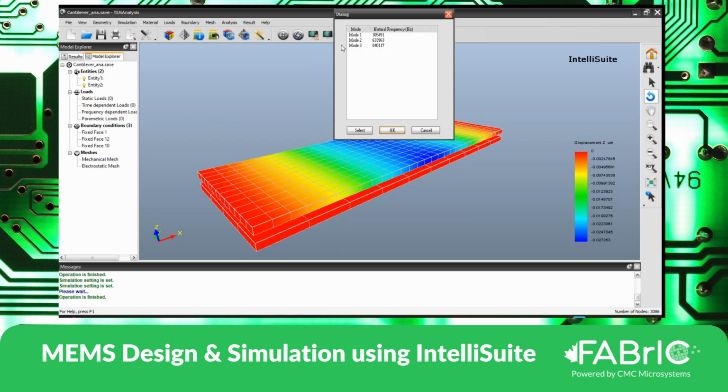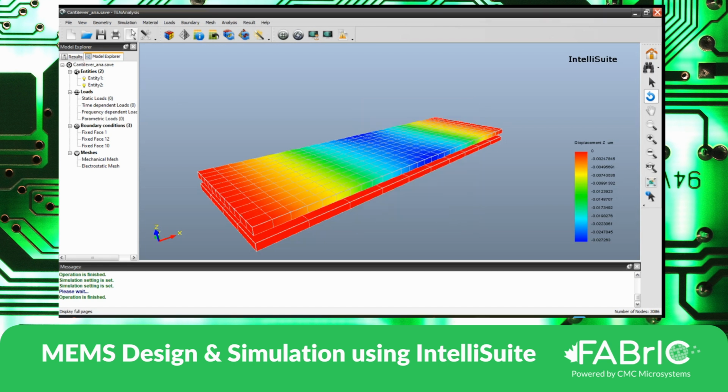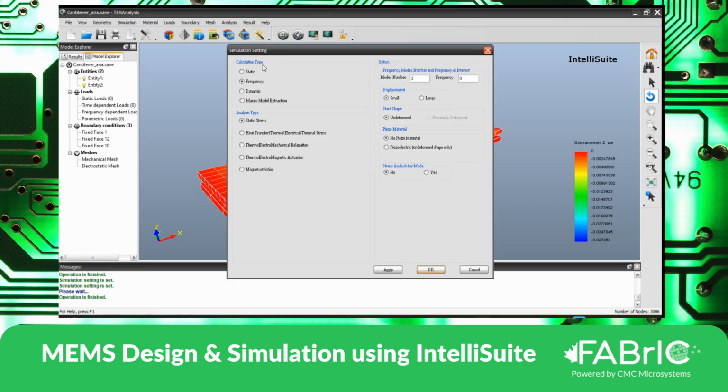The three modes of frequency are here: 305 kilohertz, 633 kilohertz, and 840 kilohertz for modes 1, 2, and 3. Why did I get three modes of vibration? Because I have selected three modes of vibration here. If I select 6, then I would still get 6.